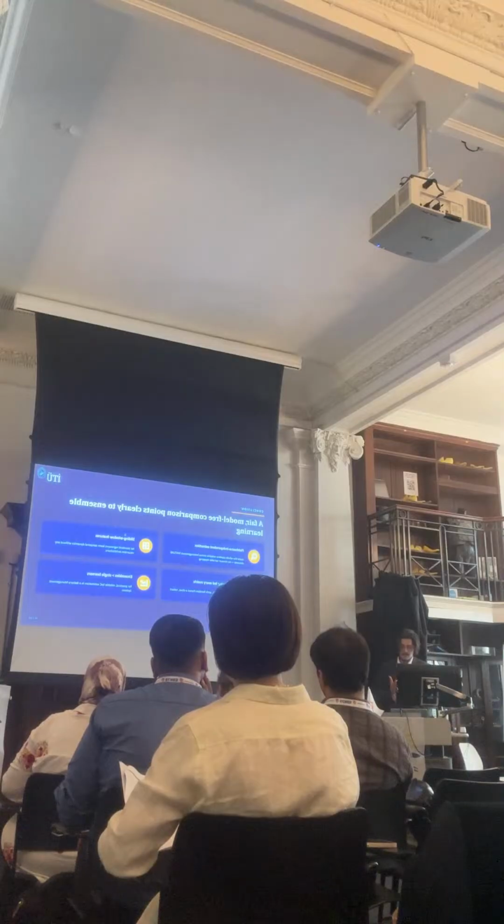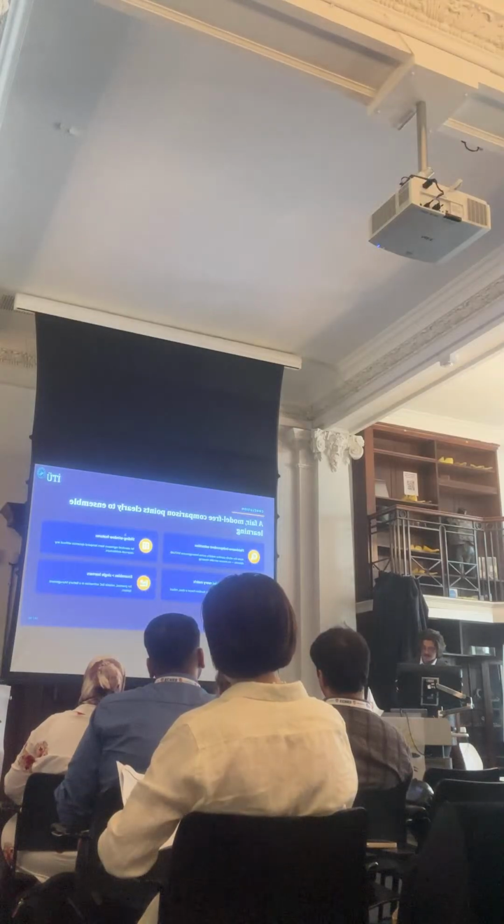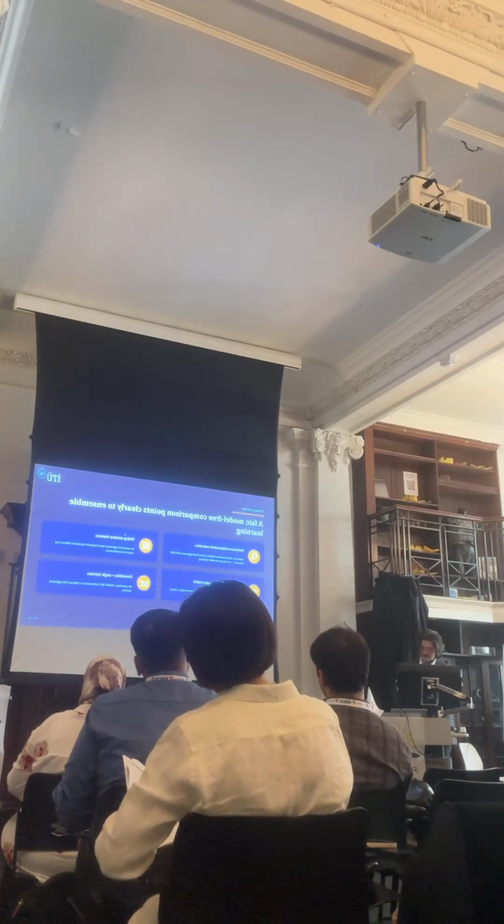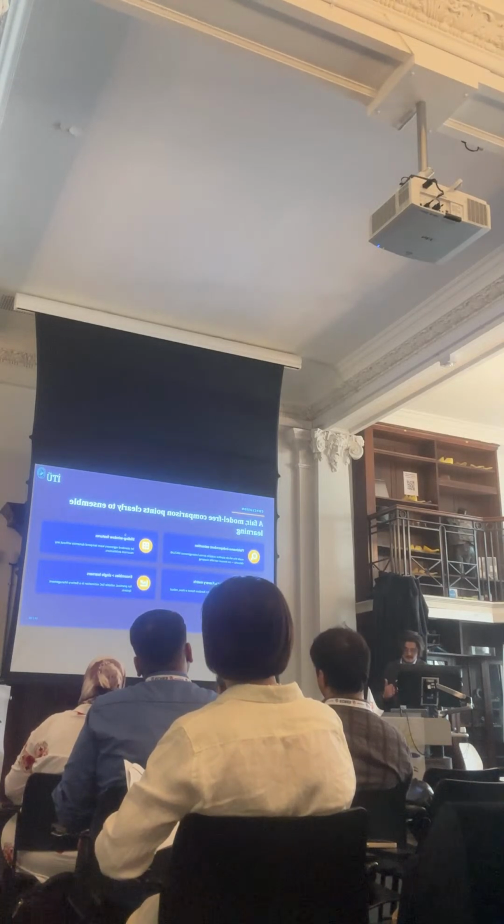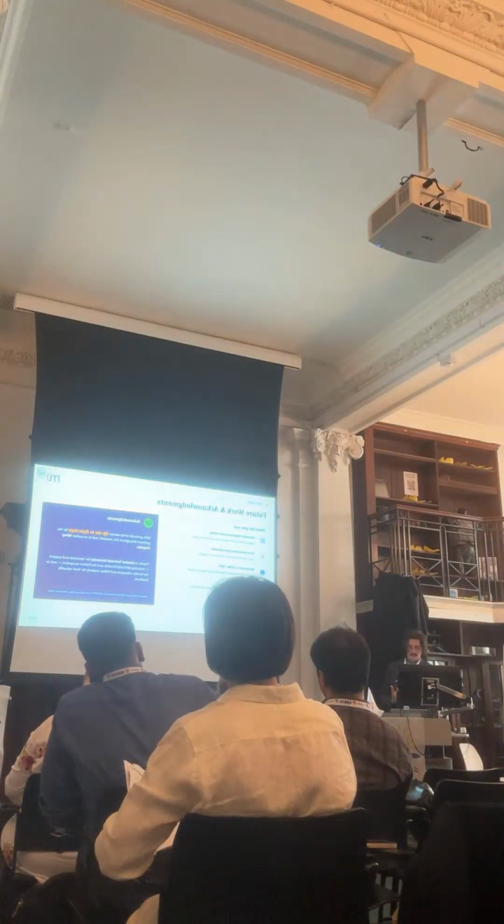All right, to conclude, our automatic feature extraction made the pipeline scalable. The sliding window lets standard regressors learn dynamics without a recurrent network, and gradient boosting wins on every metric. The clear message is that for practical, reliable state of charge estimation, ensemble learning outperforms single learners in this comparison.